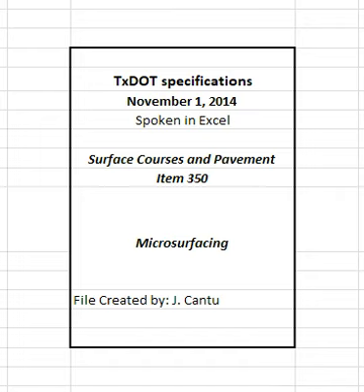4.11.1 Finished surface. Provide a finished surface with a uniform texture free from excessive scratch marks, tears, or other surface irregularities. Marks, tears, or irregularities are considered excessive if more than one is at least 1/4 inch wide and at least 10 feet long in any 100 feet of machine pull. More than 3 are at least 1/2 inch wide and more than 6 inches long in any 100 feet of machine pull, or any are 1 inch wide or wider and more than 4 inches in length.